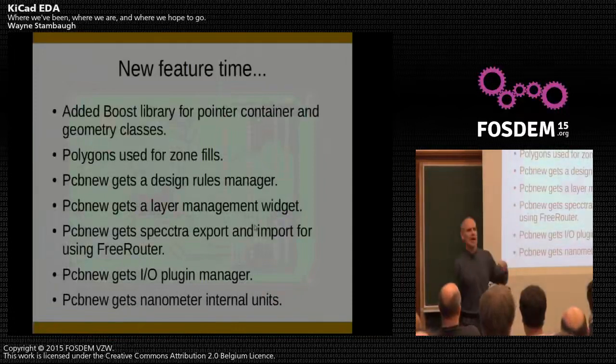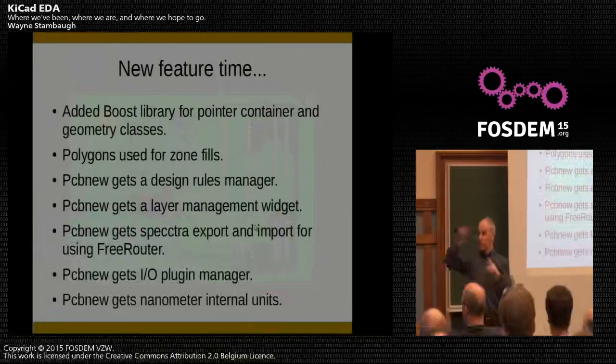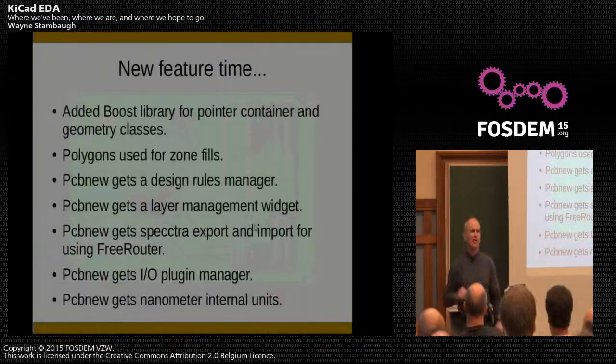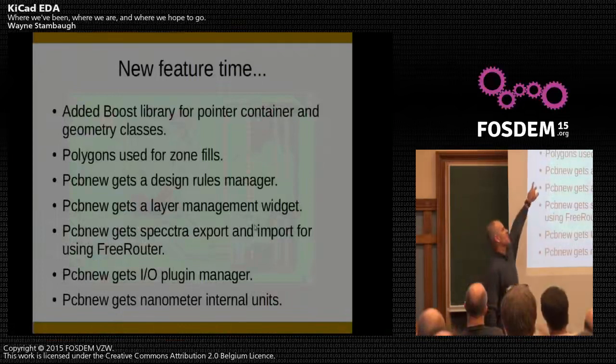Originally, the zone filling algorithm, I don't know how many people used it that long ago, used segments. So literally, you would do a zone, and it would fill with little teeny tiny segments. And if you ever had a board made, if you weren't careful, you looked at the end, you saw a bunch of little humps, where the butt end of the segment was drawing, so the Gerber output file would. So that changed. We went from the segment fill to the polygon fill.